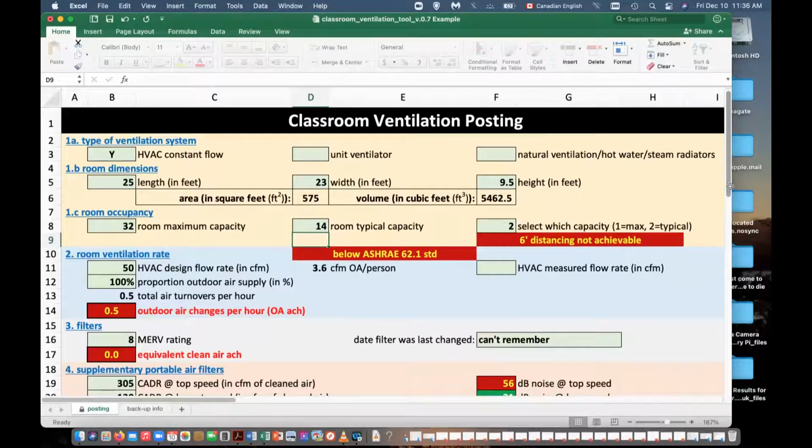Of course, in a natural ventilated place, you're never going to achieve the ASHRAE standard. It's based on a certain amount of CFM per person. Well, naturally ventilated classrooms often have exhaust fans. Right. Sometimes they're in the classroom, but they're so noisy that they're usually turned off. But at recess or overnight, you could run those in order to get some air changes.